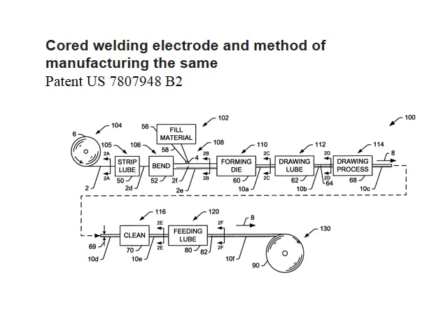The sheath or steel portion of the flux-cored wire comprises 75 to 90% of the weight of the electrode, and the core material represents 10 to 25% of the weight of the electrode. For a covered electrode, shielded metal arc welding, the steel represents only 75% of the weight, and the flux is 25% of the weight. More flux is used on a covered electrode, shielded metal arc welding, than in a flux-cored wire to do the same job. This is because the covered electrode contains binders to keep the coating intact and also agents that allow the coating to be extruded.